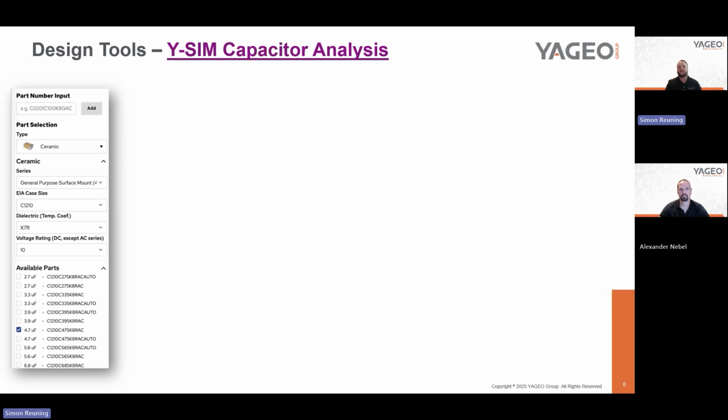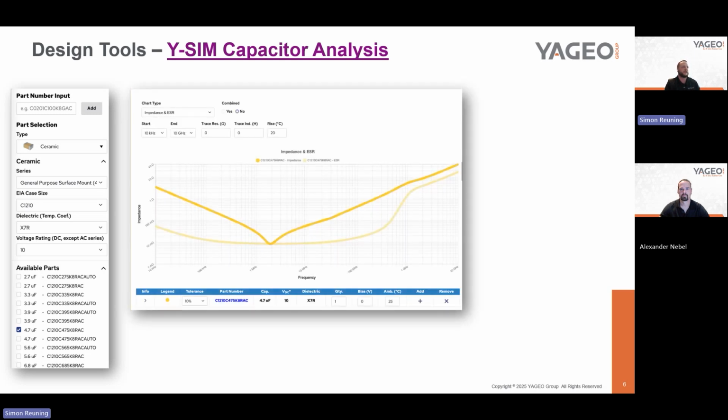It's just one click away, and you can very quickly see exactly how this product is going to perform in your application. Not to go into too much depth, go ahead and play around with it. Again, it's a free tool. You can check it out and see what it can do for you. But you have the option to really look at the impedance and the ESR over the frequency. And it's not just in a lab situation. You can simulate it based on the ambient temperature.